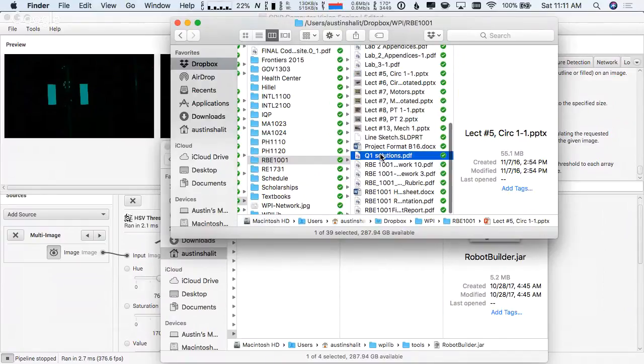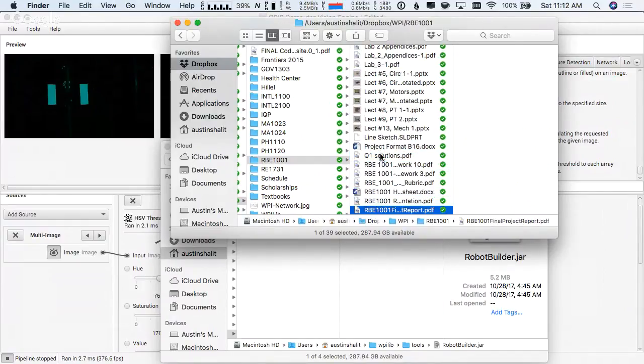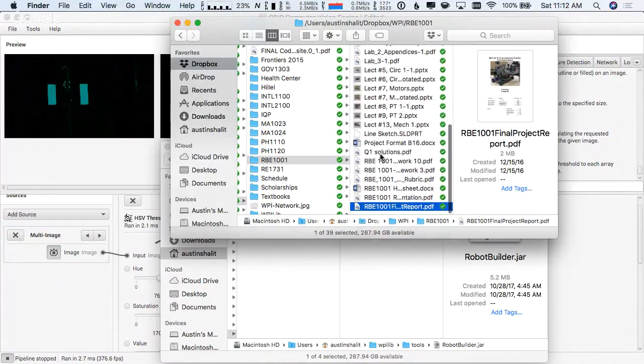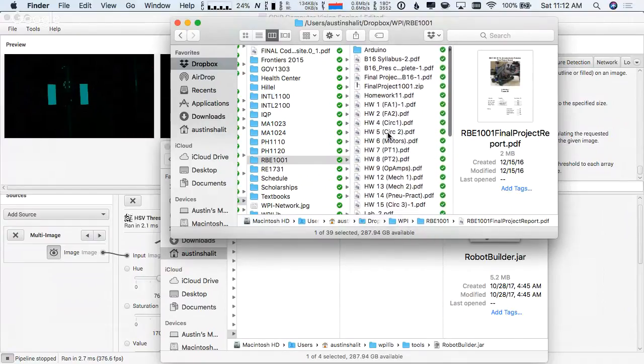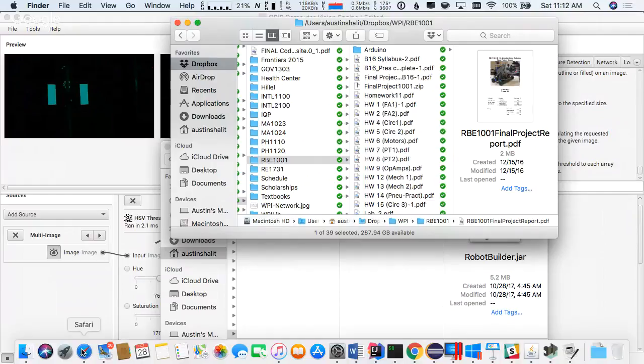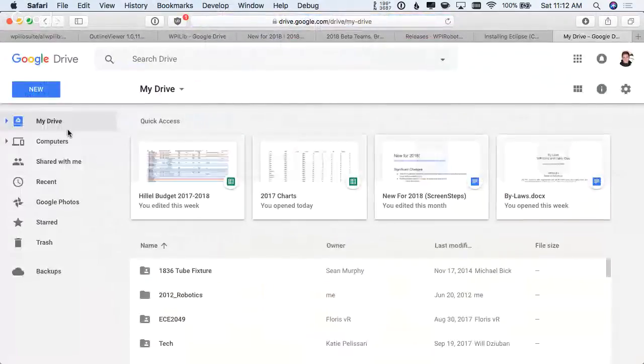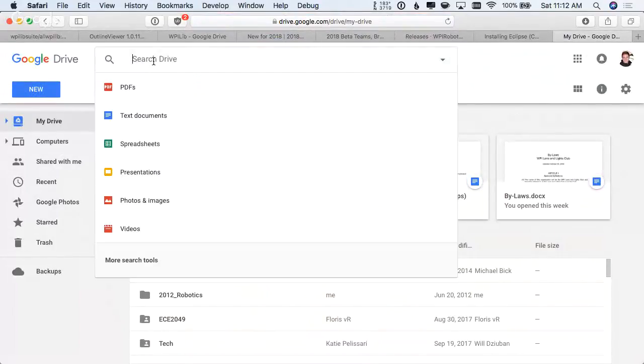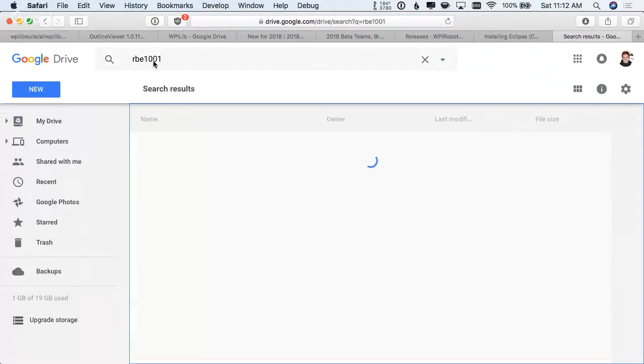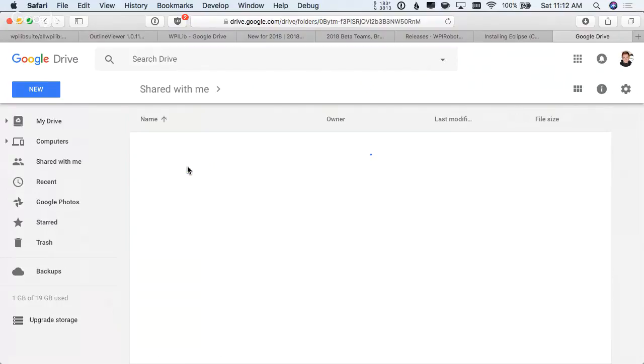So these are fun to play with, and they do really cool tricks. If you use a gyro sensor, so you can know which way the robot is pointed, then you can do what's called field-oriented driving, which is really adding a few lines of code to your program if you use the WPILib software that does the driving stuff. That means that you push the joystick forward, and the robot will go forward no matter which way it's facing.